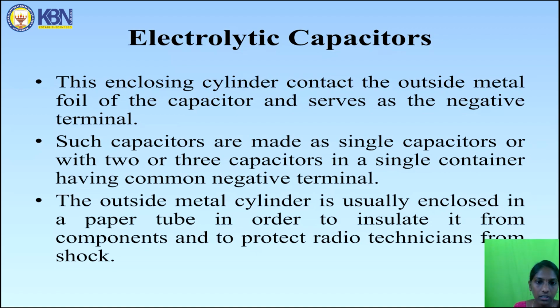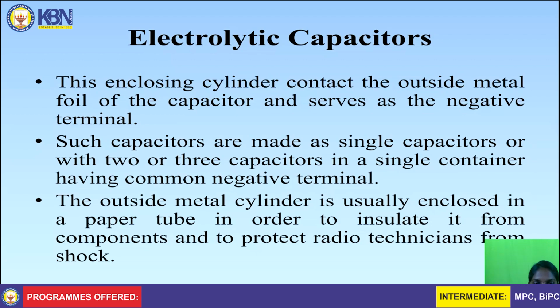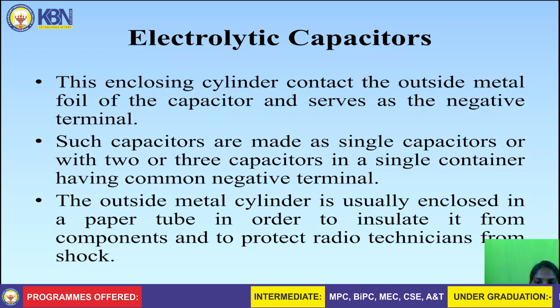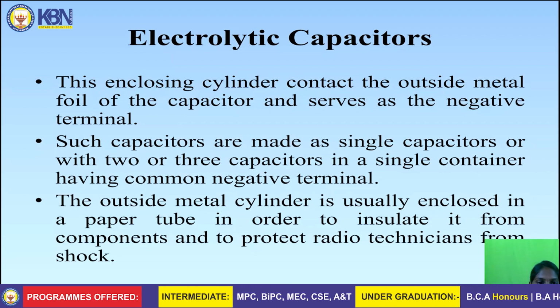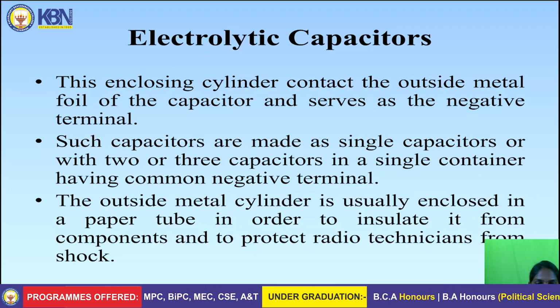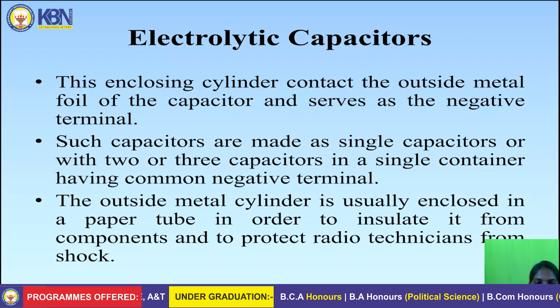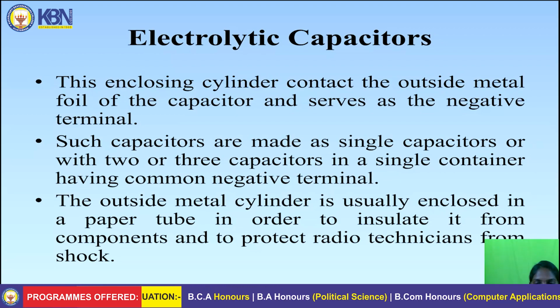Such capacitors are made as single capacitors or with two or three capacitors in a single container having a common negative terminal. The outside metal cylinder is usually enclosed in a paper tube in order to insulate it from components and to protect radio technicians from shock.